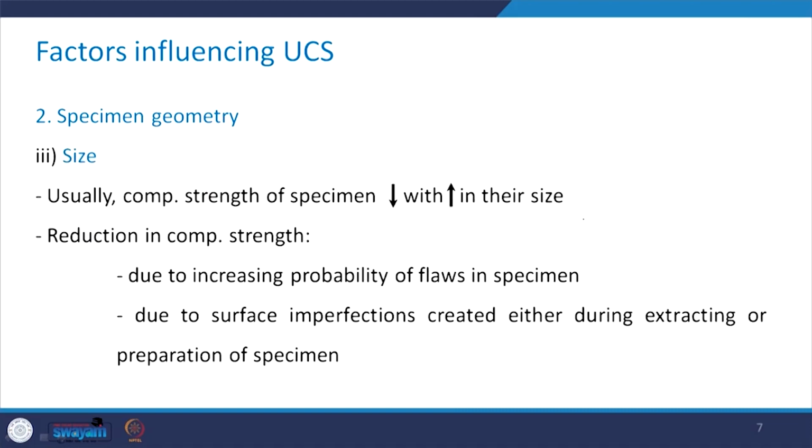Then the next is the size. In general, it has been seen that the compressive strength of the specimen reduces. So, this sign is for reduction and this is for increase. The compressive strength of a specimen reduces with increase in its size.